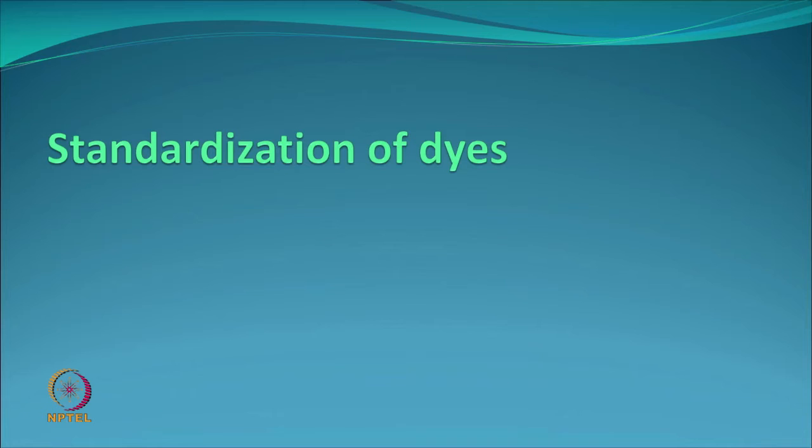So, what kind of standardization are we talking about? We are talking about standardization of the ink itself. We may like to talk about the standardization of the hardware. So, let us say the standardization of dyes, which obviously in the inkjet context we call inks, not dyes. Of course, they are dyes, but because the viscosity is very low, conventionally they are termed as inks.